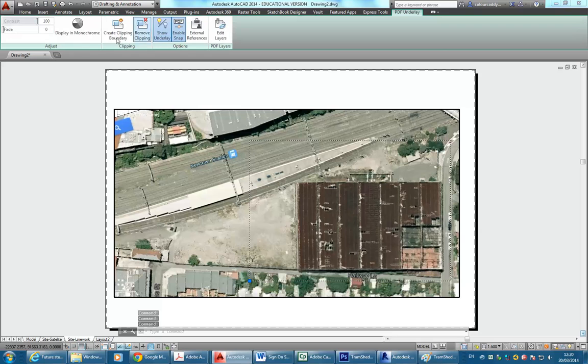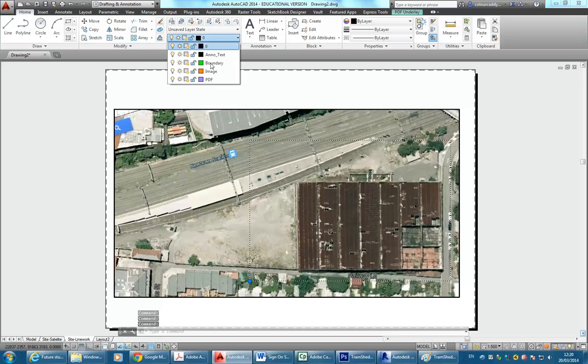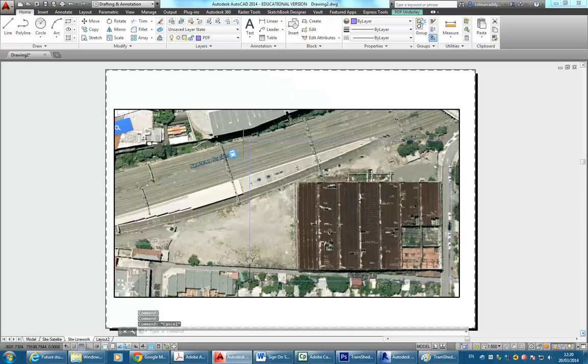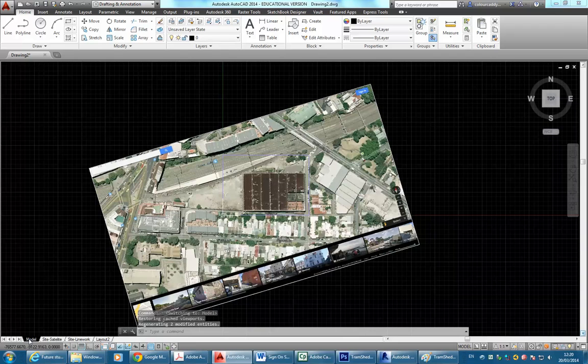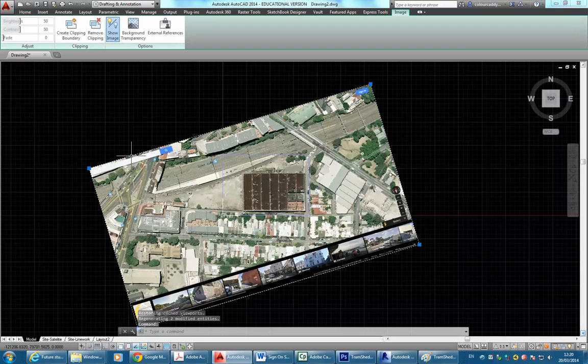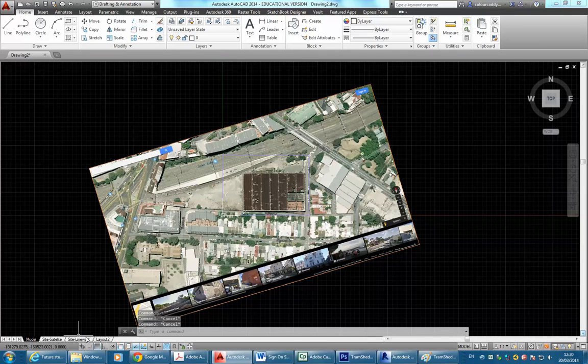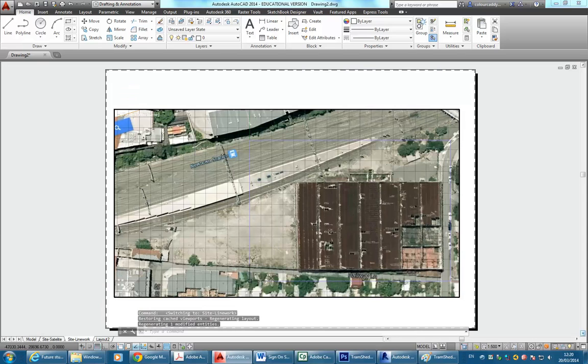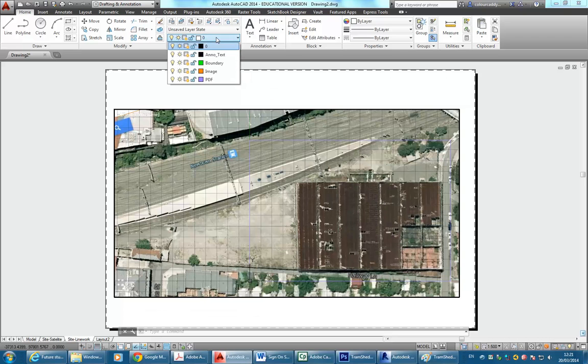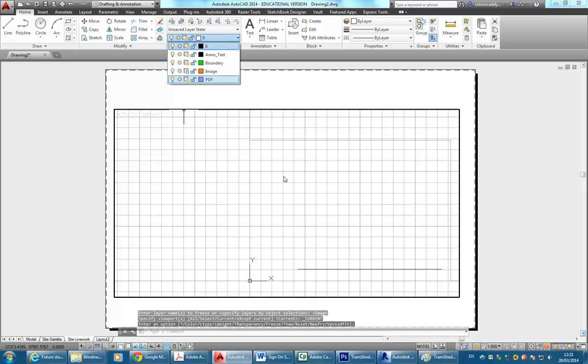Okay, so my PDF, I can move to the PDF layer by choosing it in this view. The image, I'm going to go back to the Model tab so that I can select the border there without moving the view. So here you can just change the image to the layer, and so you can see having the colours helps, so you can tell when it changes layer. And so now, if I go back to that Site Line Work page that I made, I can go to my layers and use this freezing current viewport to hide the image just in that view.